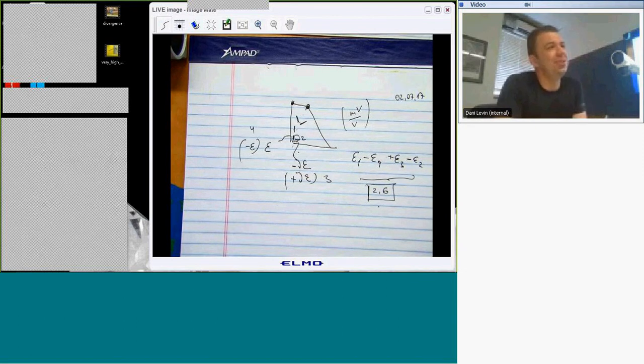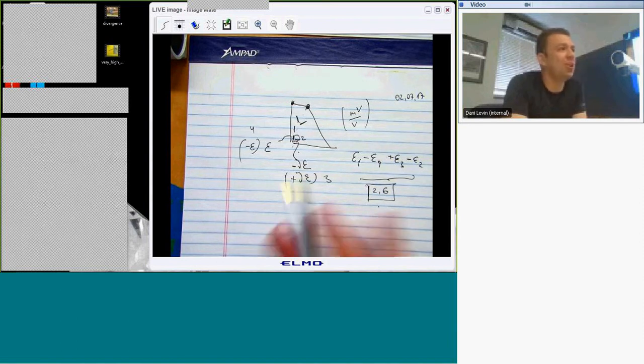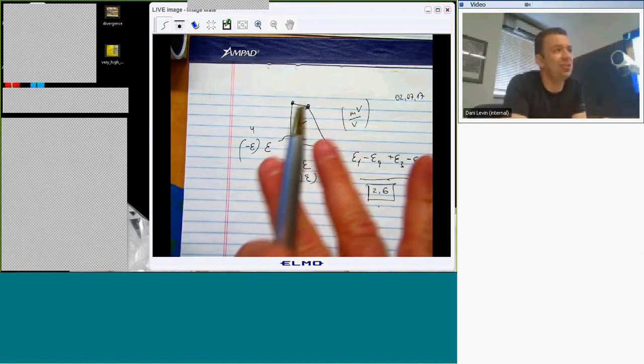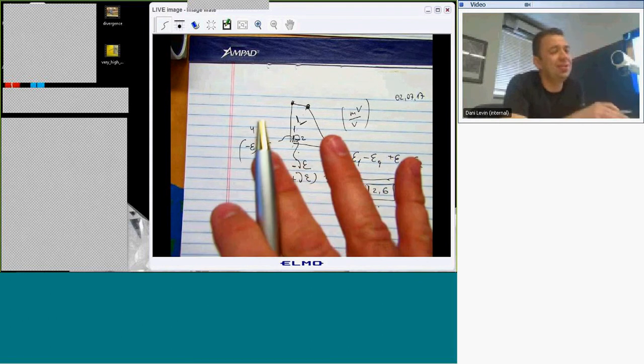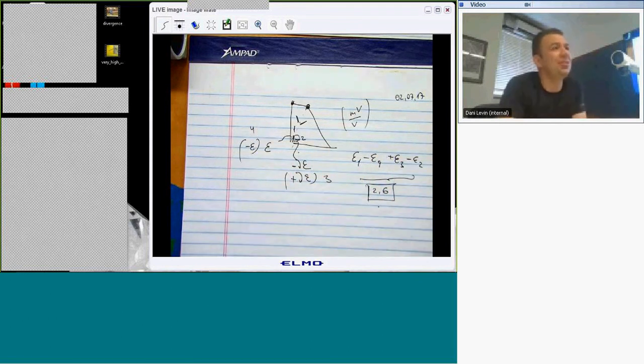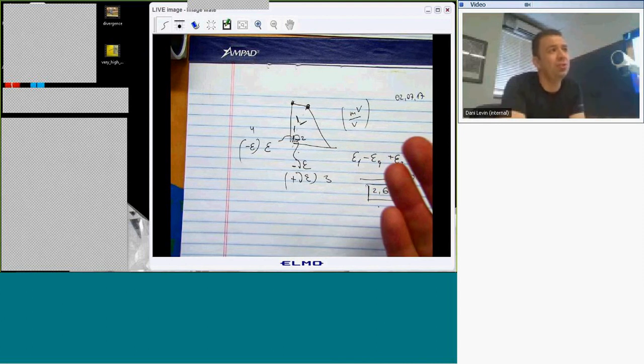The environmental guys that usually measure vibrations like accelerometers. The structural guys like strain gauges very much. This is very separated, because if you want to validate, for example, your loads model, there's little to know from an accelerometer. You can, but why would you if you can measure it directly?